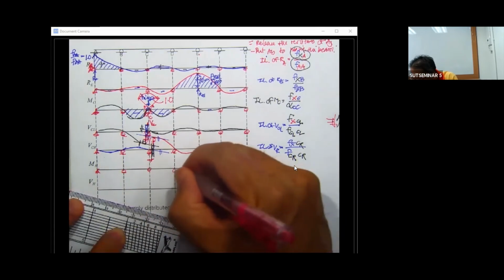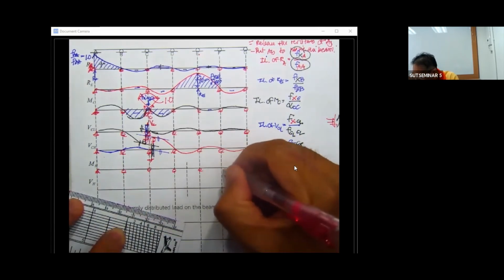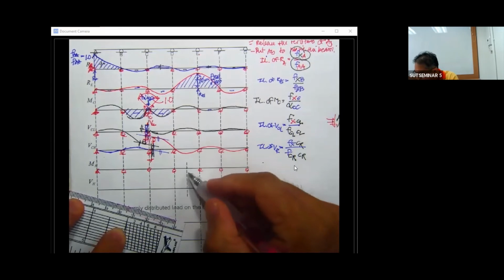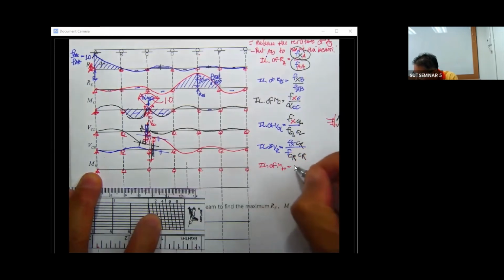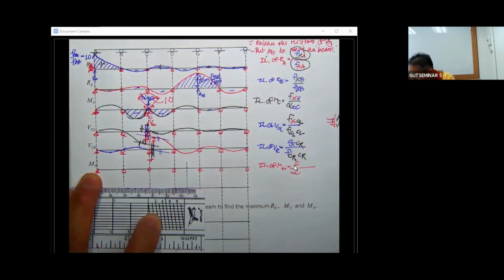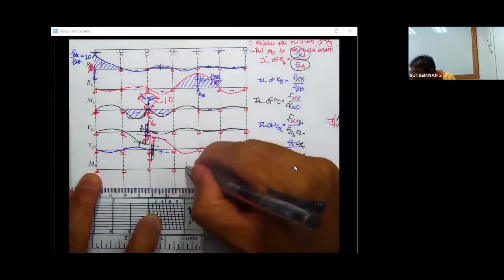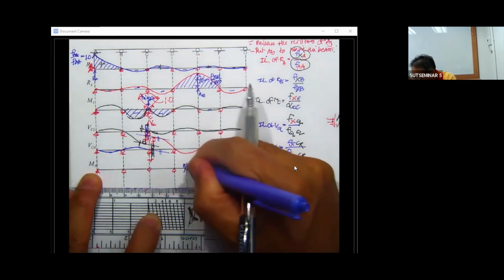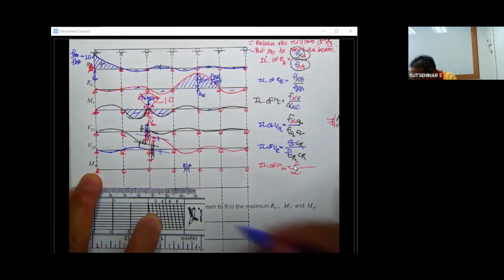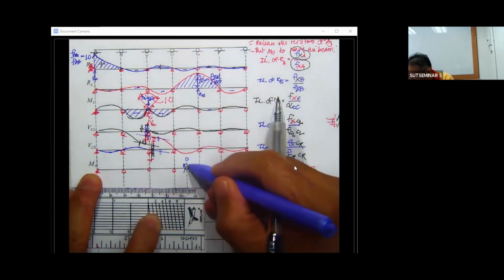And then at point H, what occurred at point H? Moment. The influence line of M sub H is going to be the deflection divided by the slope. So you put the hinge and then put the moment M sub H into the hinge. And this one is going to move. How much does it move? Not AB over L. You're going to compute the deflection of this.